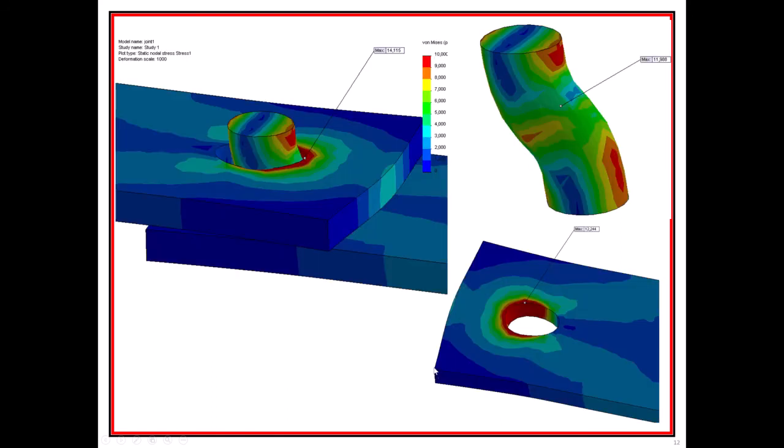And here's an FEA that I did where this is actually a little difficult. You have to be careful with your boundary conditions to be able to simulate this right here. It's a little deceptive, but you can see that the holes are getting bigger. Now, of course, this has a scale of 1,000, so I've multiplied the deformation by 1,000 just so you could see it. You could highlight it, and you could also put the von Mises stress on there. So you can kind of see that it's got some bending going on. I think the bending is influenced by the fact that I forced the head of the bolt to be horizontal. But I kind of had to do that in order for the thing to solve. It likes to crash if you don't have the right boundary conditions on it.